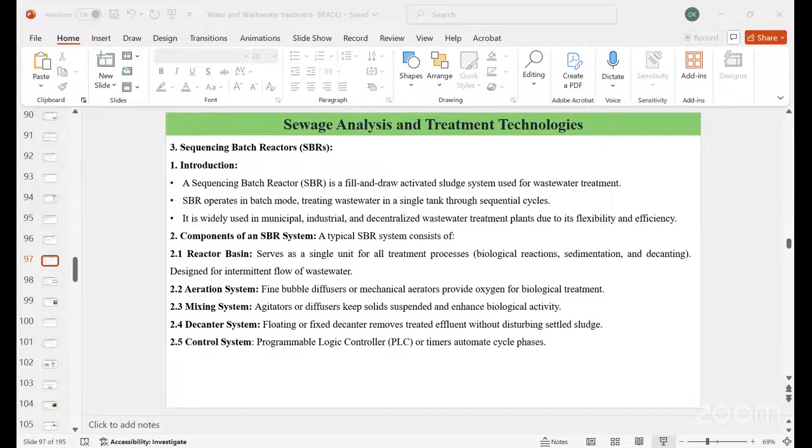The main principle behind this process is the generation of reactive species, where these AOPs rely on the in situ generation of reactive species, primarily OH radicals. And these OH radicals are particularly powerful oxidants that can rapidly and non-selectively degrade a wide range of pollutants.